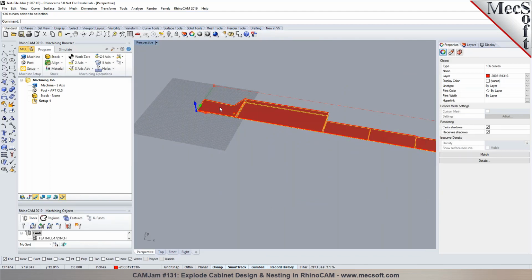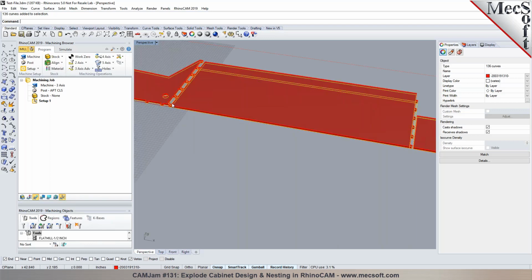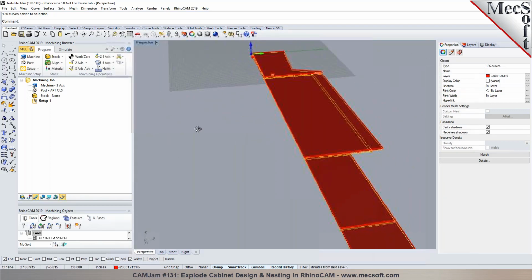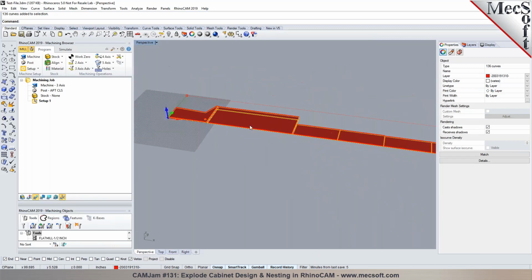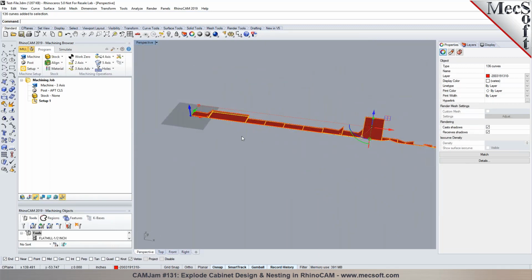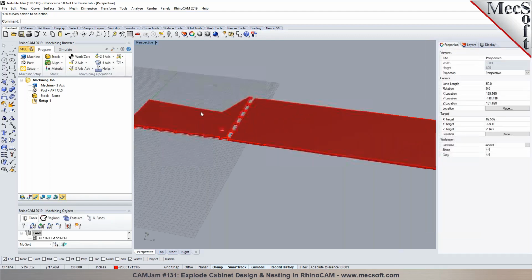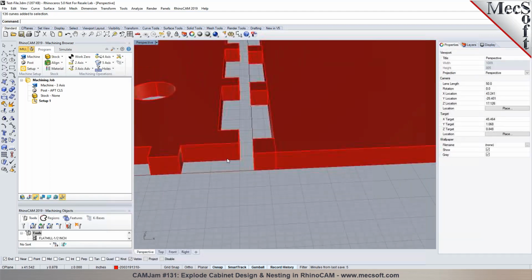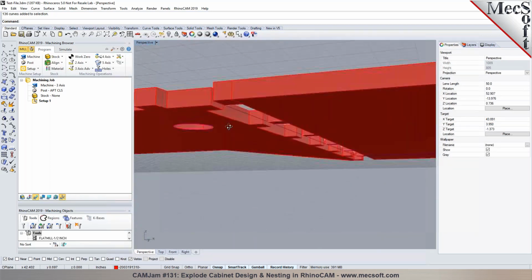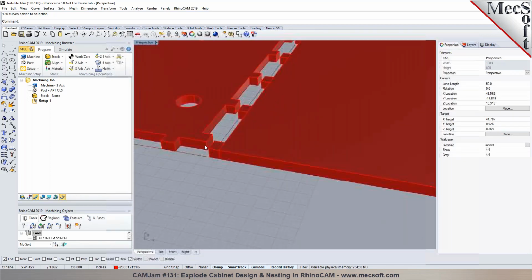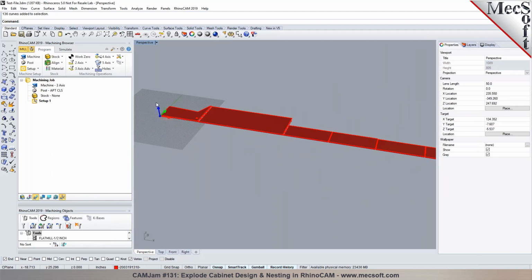So when we did the Explode Cabinet Design, that's what we call them as curves. So it'll create both the curves and the solids when it flattens it out. So since you're primarily interested in just the solids, I can choose not to have the curves. Well, actually, it's the opposite. I'm interested in the curves because the software won't read the solids. They'll just read the 2D lines. Oh, okay. All right. Then we can just do the curves.